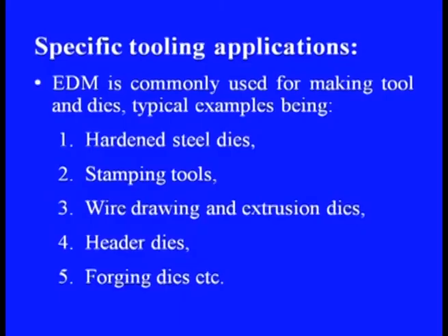Specific tooling applications of this process. EDM is commonly used for making tools and dies. Typical examples being number 1, hardened steel dies, stamping tools, wire drawing and extrusion dies, header dies, forging dies, etc.